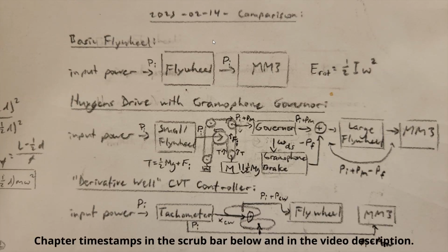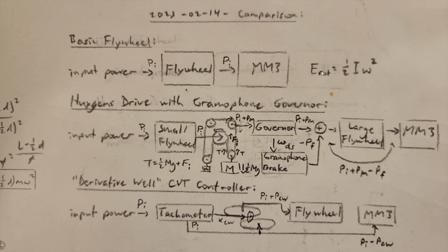When analyzing the marble machine, one can regard it as a system of multiple masses, each bearing a rotational kinetic energy equal to 1/2 of its moment of inertia, I, times the square of its angular velocity, omega. The angular velocity, that is, the rotational speed, only changes when the energy changes. Changes in energy are caused by positive sources of power, such as the user's pedaling, and negative sources, such as friction or the load of lifting marbles.